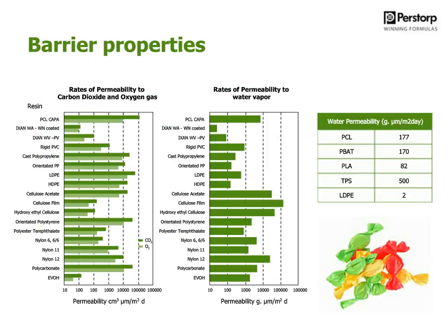When we looked at the starch blends early on, I mentioned that polycaprolactone is a very open and breathable material. And here you have an overview of different materials as well as PCL. And as you can see, it is very breathable. But in most cases, when you work with film applications, it's very seldom you just have one layer. And so many times you can combine several layers to still achieve the barrier properties that you're targeting.